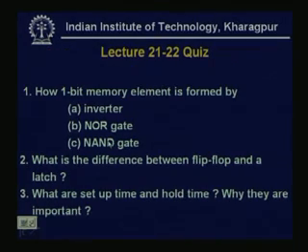Now, based on today's lecture and the last day's lecture, there can be some quiz questions. First, how is a one bit memory element formed by an inverter, NOR gate and NAND gate? Second, what is the difference between a flip flop and a latch? Third, what are the setup time and hold time, and why are they important in real life circuitry? So, these are the three quiz questions that are mainly based on the last two lectures.